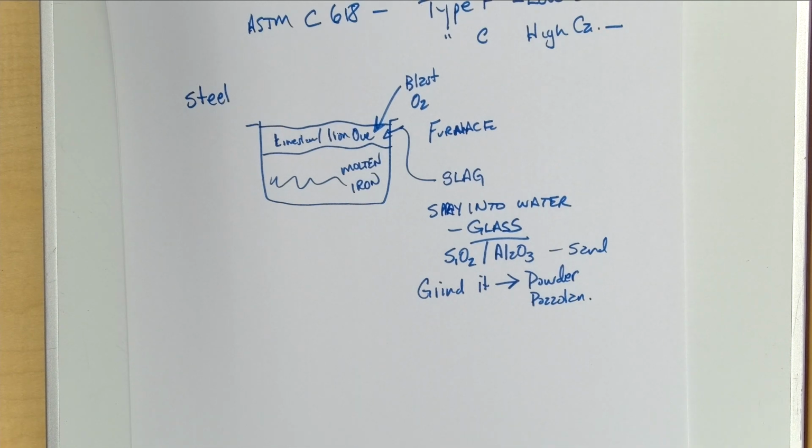It's a very interesting material because it's latently hydraulic. At room temperature, it'll react just with the water, but it takes a lot of time. At 140 degrees, it's taken off like a rocket and reacting all by itself. So it has latent hydraulic capacity. So if you do something that gets the concrete hot, up in the 100-degree range, then the slag starts to behave as a hydraulic cement. So it's kind of both.